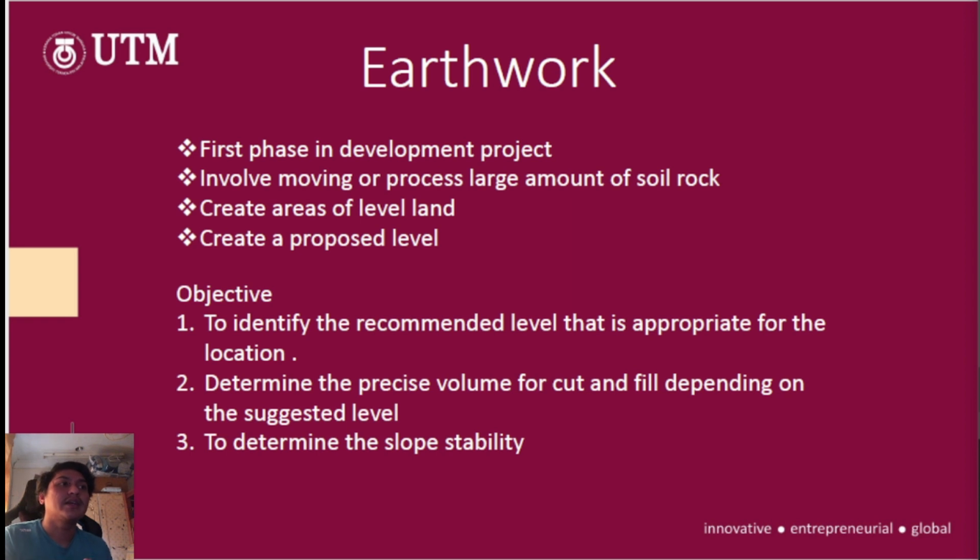Earthwork is done to create areas of level land that are suitable for housing, business, and recreation, as well as the necessary gradient for paths and roads that allow people to travel from one location to another. The objective of this earthwork is to identify the recommended level that is appropriate for the location. Second is to determine the precise volume for cut and fill depending on the suggested level. And the last is to determine the slope stability.